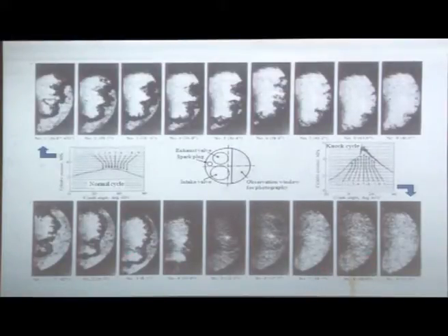Let's see, this is the cylinder pressure on the y-axis, crank angle degree on the x-axis, and you can see this is very smooth pressure. So this is at 26.6 degrees after top dead center, 29.2. It's moving very smoothly. So you can see that this unburnt charge is being consumed very gracefully. It's consumed almost 41.2, 41.6, 45. At 45, everything is consumed. No abnormal combustion is seen in any of these pictures, and the P-theta diagram is absolutely smooth. Now come to the bottom side.